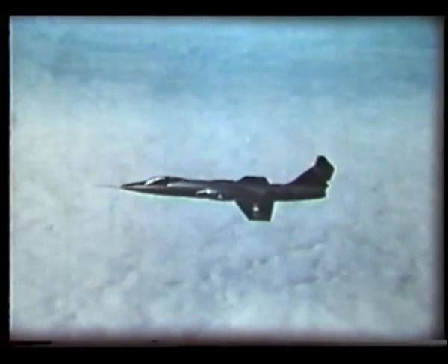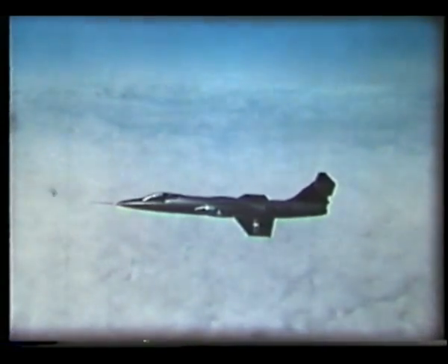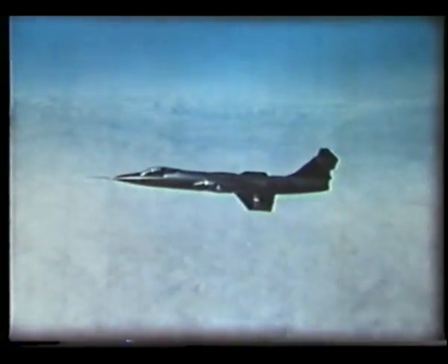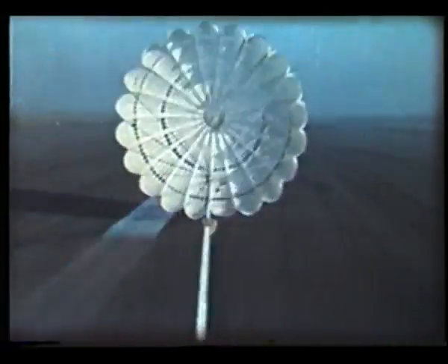At supersonic speeds, a high lift coefficient is not needed, as the speed is high enough to give the aircraft the lift it needs. But a low lift coefficient brings severe low-speed problems, high stalling and landing speeds. So very long runways and sometimes extra braking devices are needed for aircraft with these supersonic wing sections.